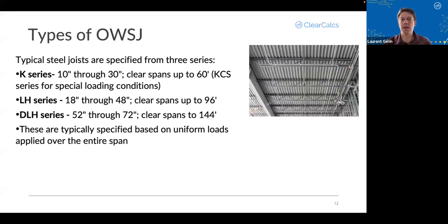Big thing here, these are typically resisting uniform loads. So you're thinking about your 20 PSF dead load, 40 PSF live load, or 100 PSF live load, whatever that might be. Typically, you would be resisting a uniform load with these.